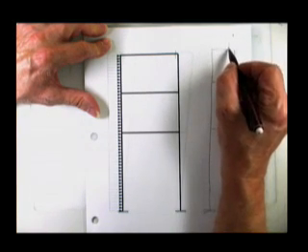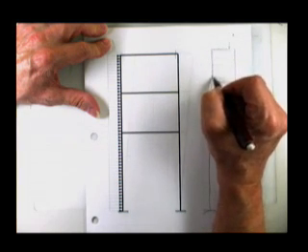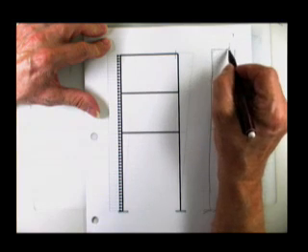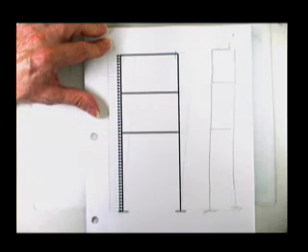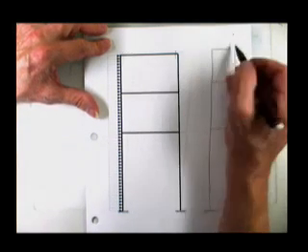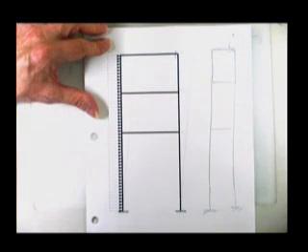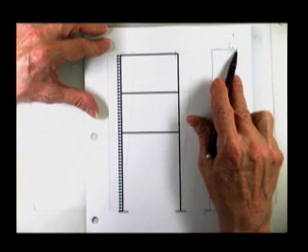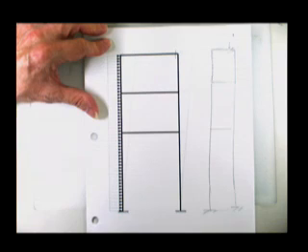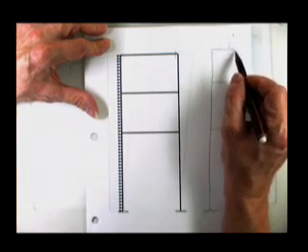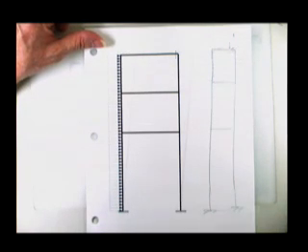because if I put a load here, I can tell you the moment, force times distance, force times distance, force times distance. If you were to put a horizontal force on this one, I could draw you the moment diagram, and I would put a corresponding horizontal force on that one, because there's no way you can do this unless you do that. Because if you say that's there, then that had to be caused by somebody, and the person it was caused by is this guy here. And I can multiply force times distance. I'm good to go till I get down in this piece here, and now I got problems again.